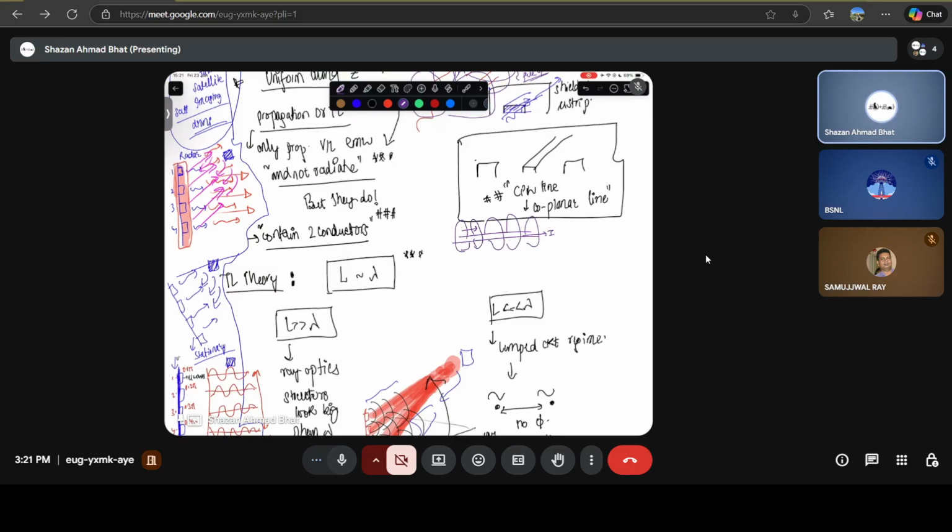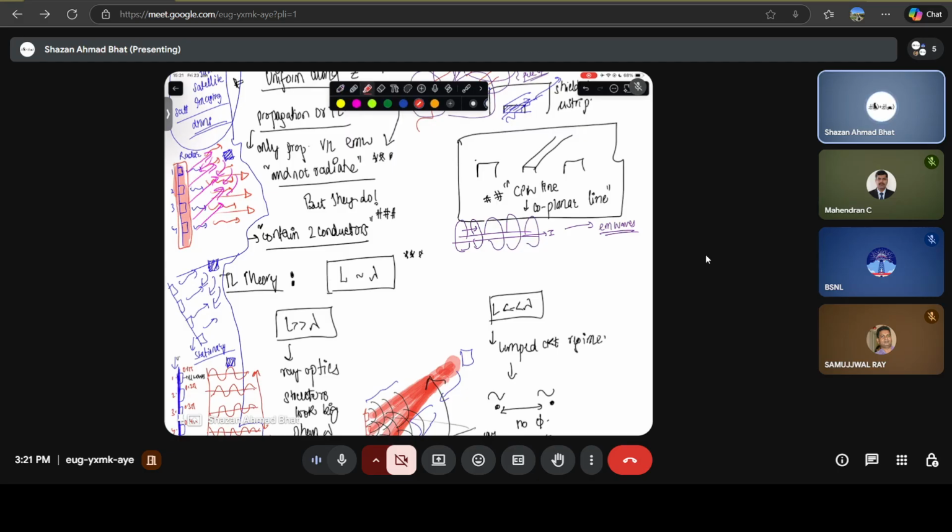And then you also know that this particular current creates the magnetic fields, and this also behaves like an electromagnetic wave propagating throughout this system. So whenever you have this electromagnetic wave propagating, it's not only localized in this particular wire. The fields are basically coming out from the wire, and they are also in free space.